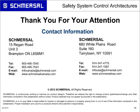All right, I've tried my best to explain this verbally. It's definitely easier to see on paper. What happens is, let's assume that you just have 2 door switches wired in series with one another. So when you look at a safety circuit, you'll have door number 1, channel 1, wired in series with door number 2, channel 2. That's your first string going to S11 or S12 of the safety relay. Then you have the second contact of door number 1 wired in series with the second contact of door number 2 going to the second enable string for the safety monitoring relay.